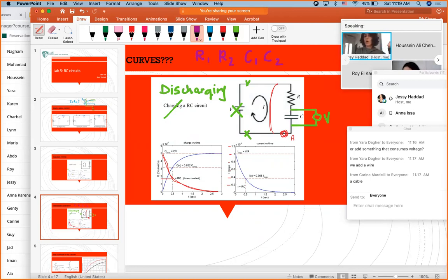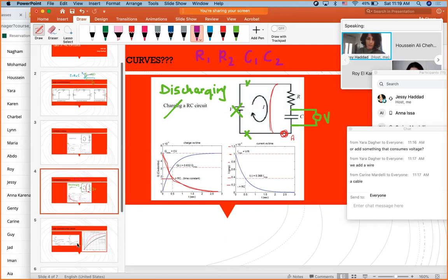And then you're gonna do R1, C2, charge, discharge, R2, C1, charge, discharge, R2, C2, charge, discharge. Then you're gonna do C1 and C2 in series with R1 and do the charge, discharge, and then C1, C2 in parallel. And with R1, by the way, R1 is always in series with them, and you're gonna find the charge and the discharge. So all these combinations, okay?